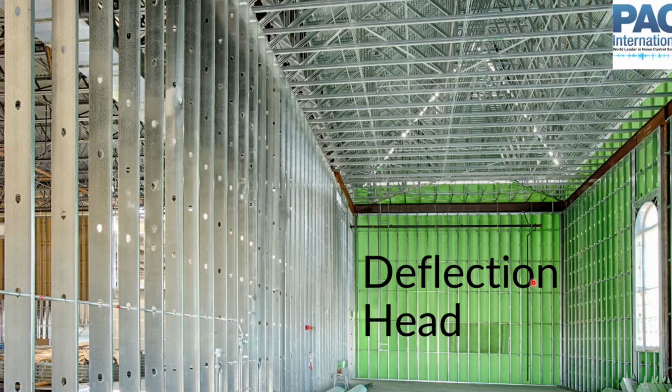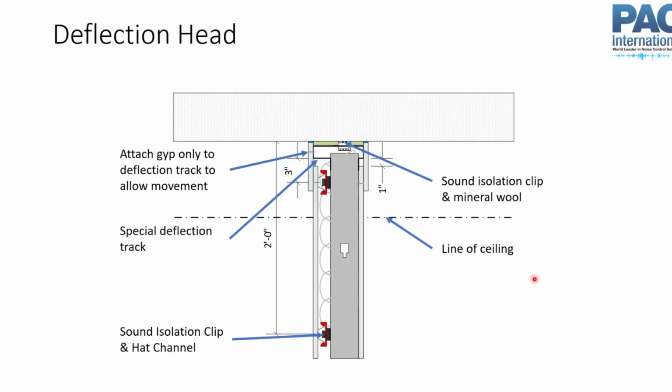All right, another example here of a structural path that we need to look at is deflection heads. And I realize there's probably not a deflection head in here, but I wanted a picture that had a bunch of steel studs in it, and this is what I could get that was free pictures I could use. So here's a deflection head detail. So when we have this, we need to decouple the wall from the structure up above.